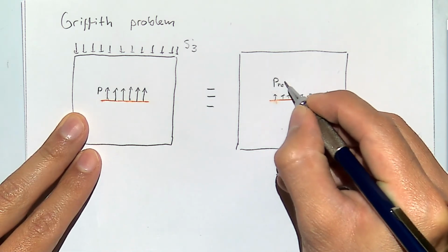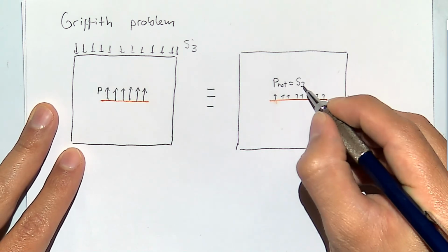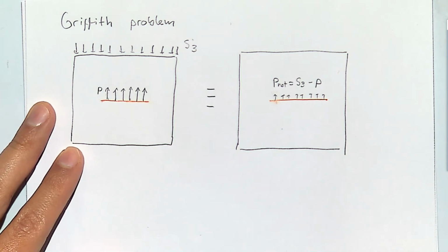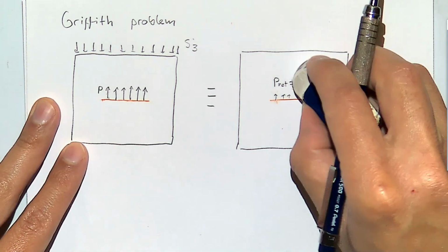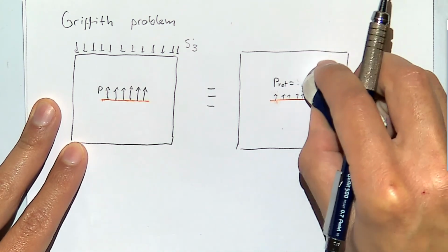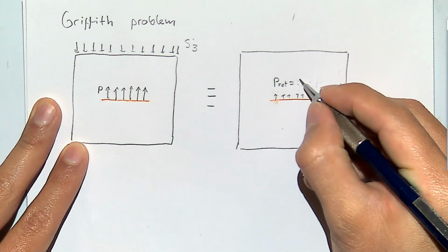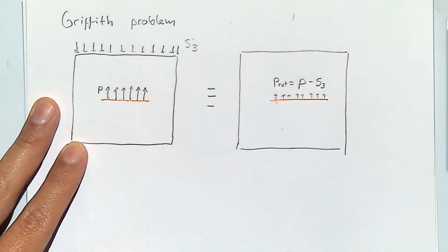The net pressure is going to be the difference between the far field stress and the pressure within this fracture. Sorry. I have problems with signs today. Thinking too much on the chopsticks. It's going to be the difference between the pressure in the fracture and the far field stress.